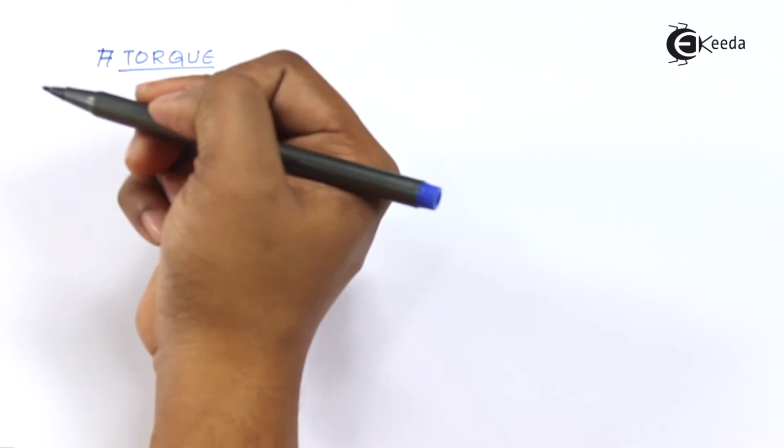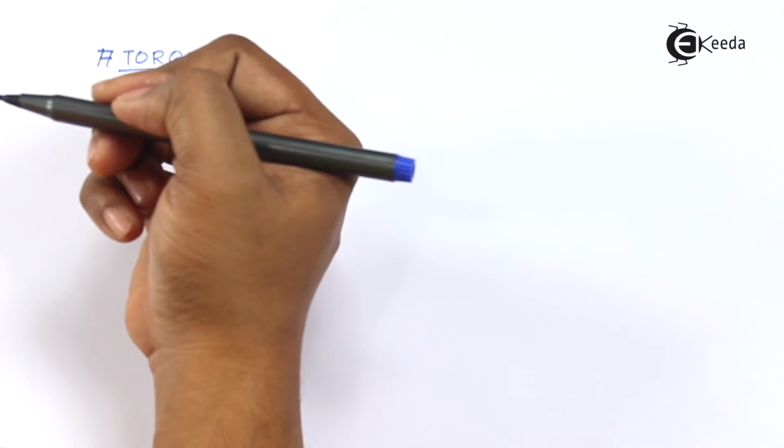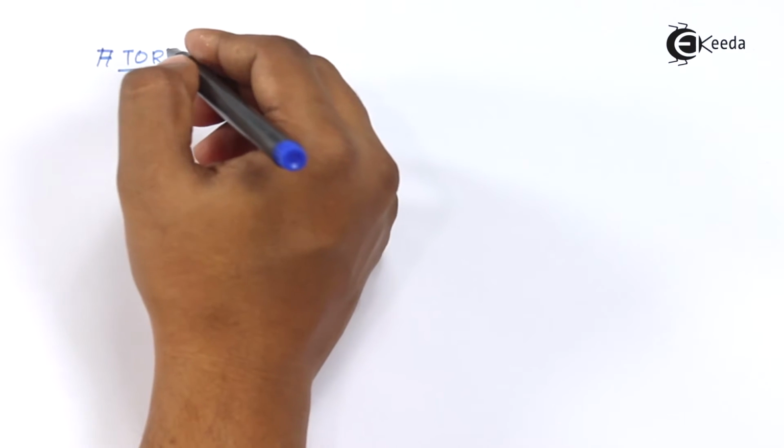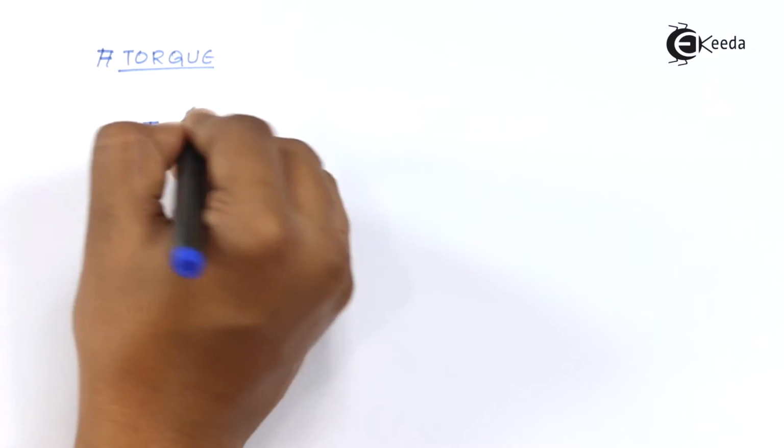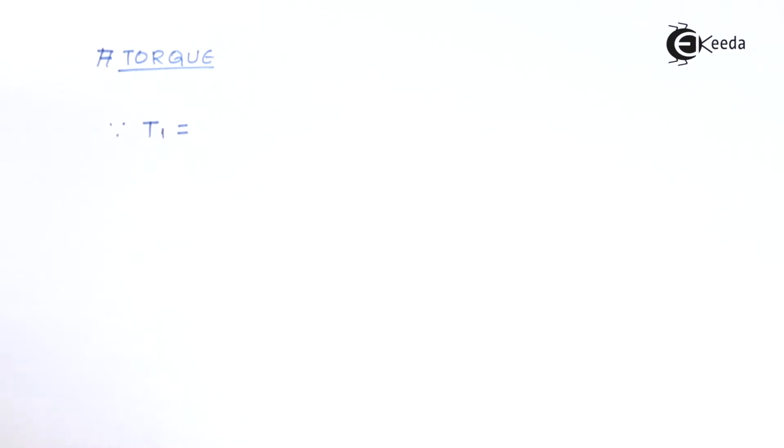Now this is the torque which will be acting on the given screw press based on the given input values and the found design parameters, right? We have to see whether the screw press which we have selected, the material which we have selected, is safe to carry this torque or not, and that's why we need to find out the torque first. So the formula, again you can find in the PSG design data book, I am referring to that.